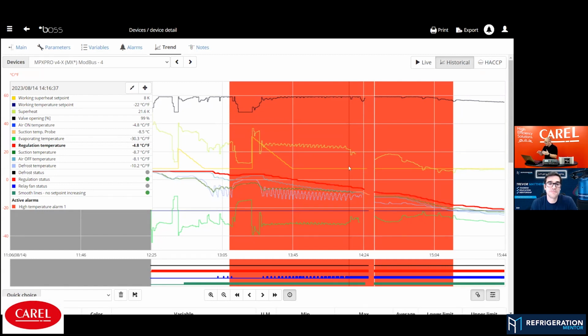And we checked a little bit more and we see some strange behavior of our fan. Below here, I will highlight it for everybody who is watching. These blue parts here are the behavior of our fans. And the stop signal of the fans comes from the door switch. So something is wrong there.